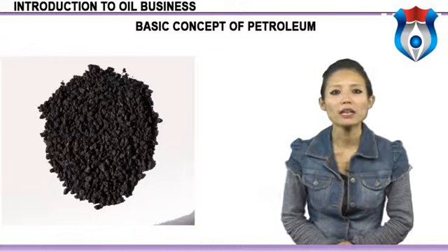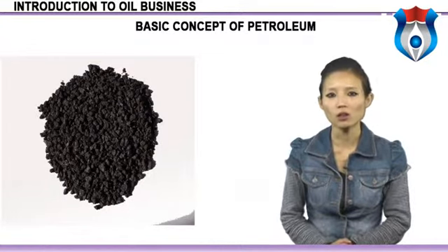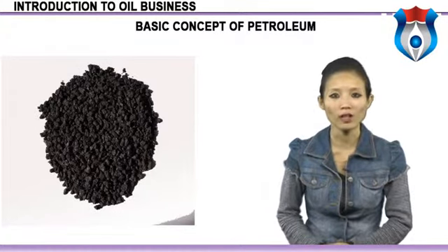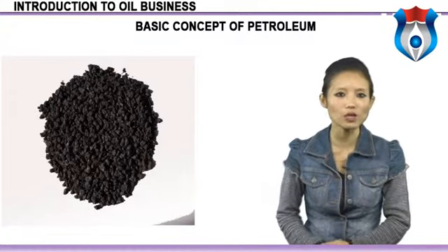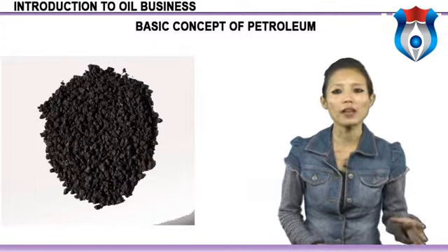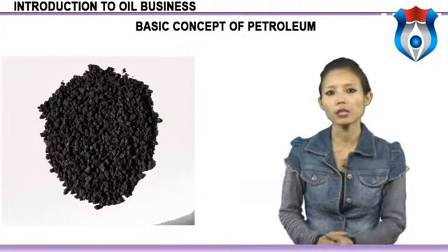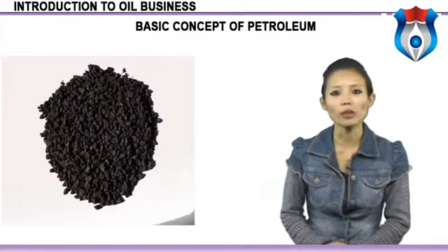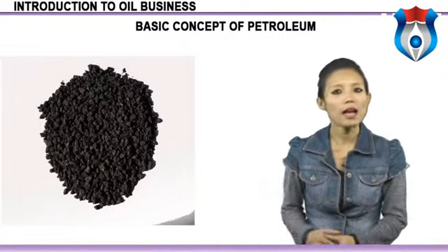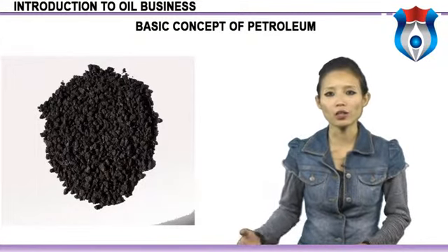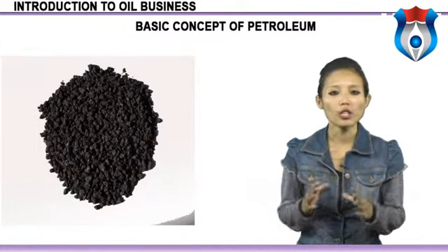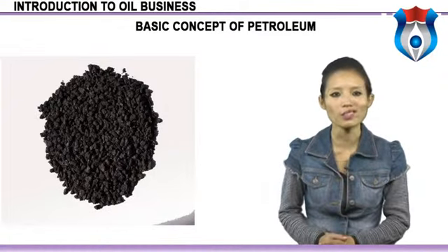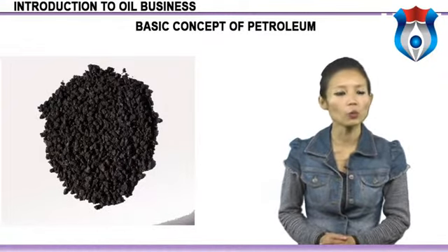In addition, many sulfur compounds might be present in these oils. They are called young shallow crudes. Young because they have not had the time to be broken down by the high temperature inside the earth, and shallow because they have not been buried deeply. Typically, young shallow crudes are highly viscous, high density materials with high sulfur content. As the oil is buried more deeply inside the earth's crust, it is exposed to higher temperature. As a result, the molecules can break apart to a greater extent, and some of the molecules containing sulfur will be destroyed.